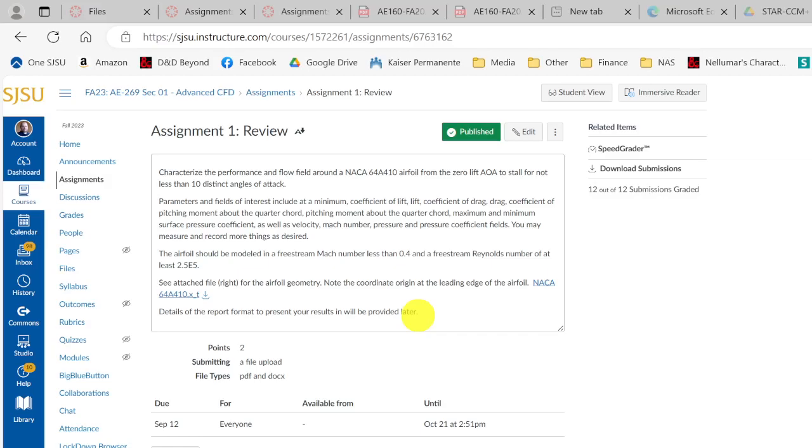That will result in weird behavior from a conceptual standpoint. It's going to get hot because it's going to be hard for flow to move through that gap, but that doesn't fundamentally make it invalid. It just took a lot longer. You're going to need more iterations and a finer mesh. Correct, yes. So was that necessary? No. Is it still perfectly acceptable? Yes. To answer your question, I clearly haven't gotten them graded yet.